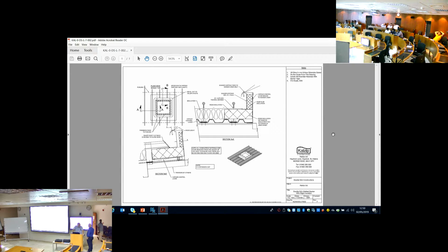But that's the thing as well. What I've noticed that we do over here is that a lot of the installations are foil faced. Someone was saying that yesterday. So foil faced at that site prevents the ingress of moisture into the insulation in the first place. So it'll be rock and it'll have foil bonded to it. And the foil we put on the outside.